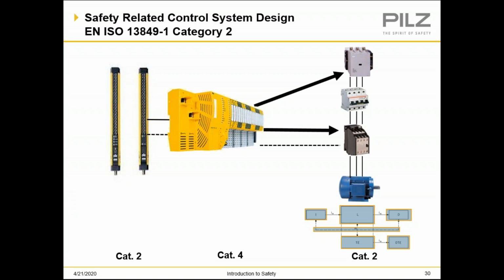If it finds that that contactor can't break the safety circuit, then it defaults and goes back to this contactor and shuts down the entire system. So this one would feed multiple of these, multiple motors. So it goes upstream from it and shuts off the main contactor to break the safety circuit.